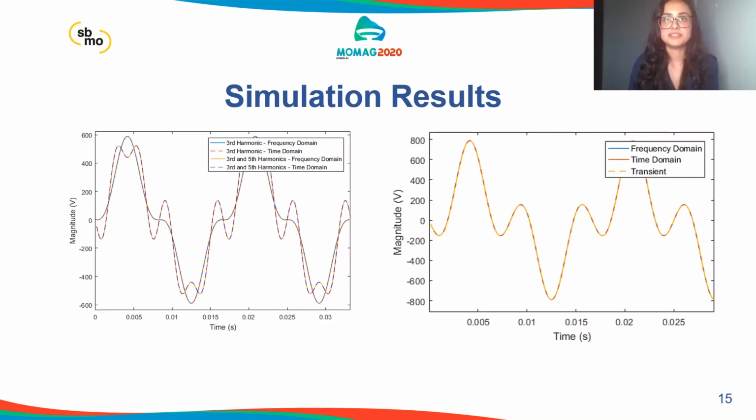By developing the analysis, it was observed that the number of harmonics injected into the system is directly proportional to the number of unknowns in the PAC simulation. For shooting method simulation, the shorter the time step, the greater the number of iterations needed to converge on a response.